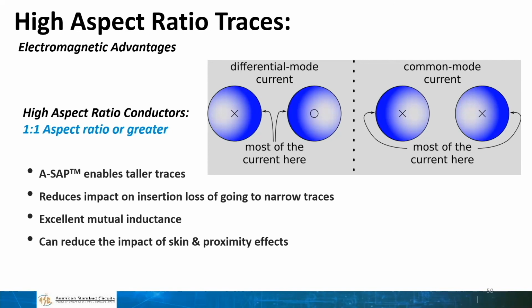And those inside edges, remember, are perfectly smooth because they're defined by the photolithography. So you can leverage the full height of the conductor. You can leverage that smooth inner wall surface as well. And you can get true differential behavior, which, if you've been designing in subtractive processes, is virtually impossible to get the way that most differential traces are designed today. So anyway, that's part of what we're going after. I think the next slide might show this in more detail or in a better way.